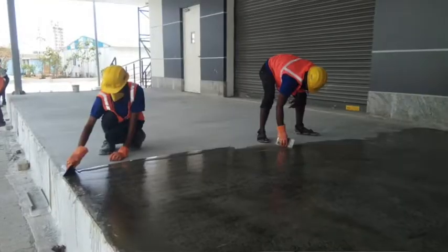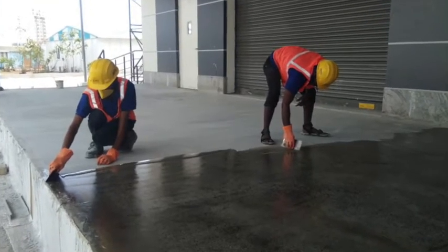The second important step in the initial grind that you need to look at is ensuring that all cracks, all pinholes, all grooves must be addressed at this stage. Because beyond this, you don't really work on rectifying the floor. This is the stage wherein you rectify. So it's really crucial that this stage is followed perfectly. If you've seen the images, we are actually using an epoxy to fill even the micro pores.